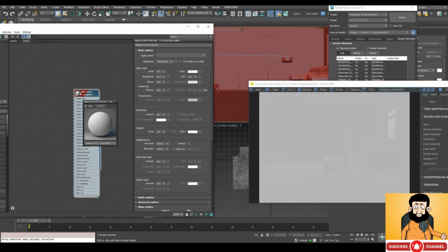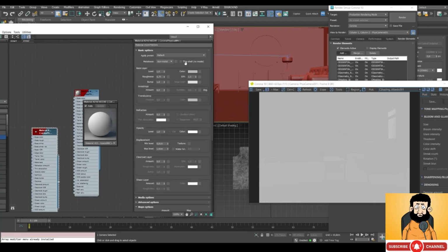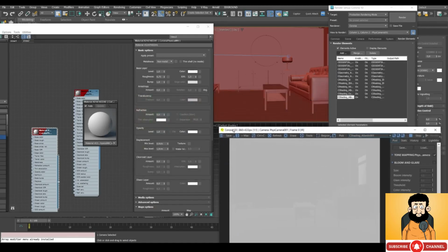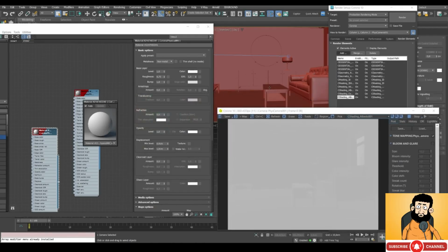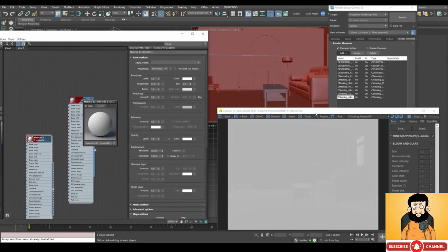So let's create a material with an incorrect albedo value. Suppose a beginning visualizer set it up wrong, and we assign this material to the table. We have the override option enabled, so we need to exclude the table from the override option.